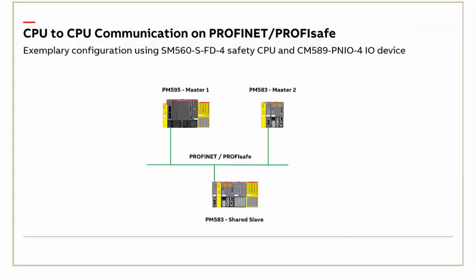So the configuration is complete. After restart of the system, we shall observe the blinking of the safety output modules on the slave and master 1 system, and then blinking of standard output channels on the DC5 to 3 non-safety I/O module. The source of this information is coming from the master 2 system. So you can imagine that in a similar way you can also create more complex communication.